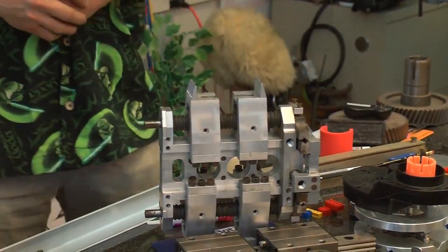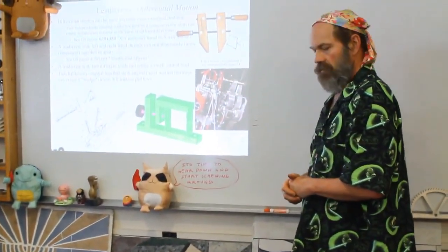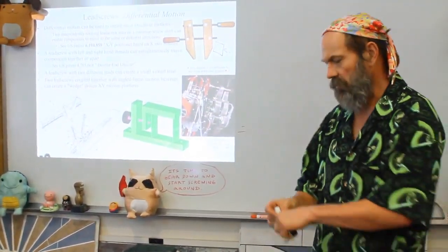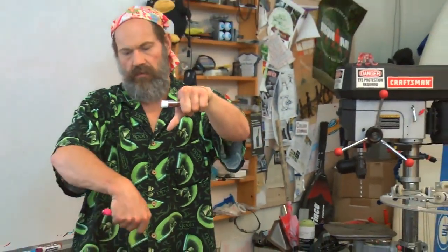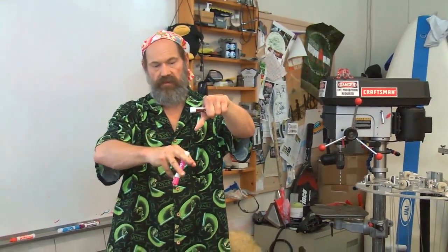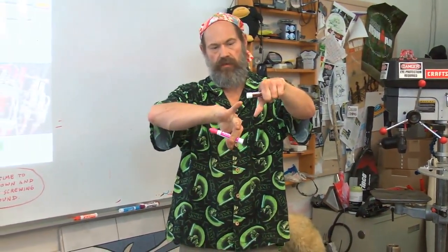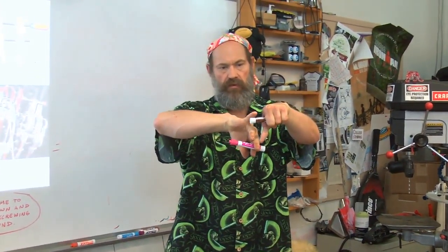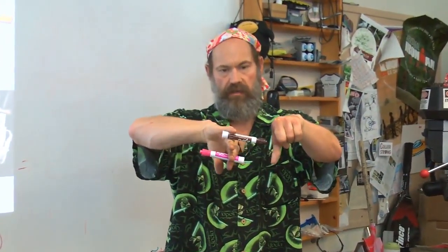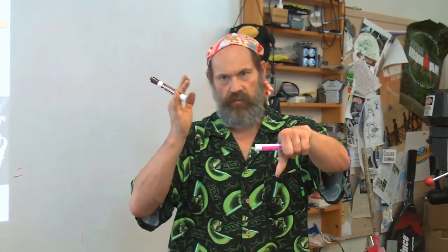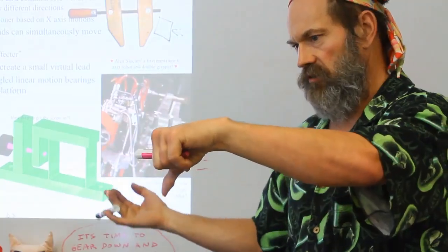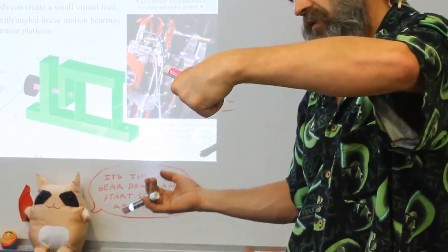Two grippers, such that in a lathe, I could have one part being finished on the lathe. The gripper comes in, wish I had more fingers, and grabs the part, takes it out of the lathe. The robot wrist puts in the unfinished part, goes to take the finished part away and put it down and grab a new part while the lathe turns on right away and starts machining. Hence the desire for the double gripper.